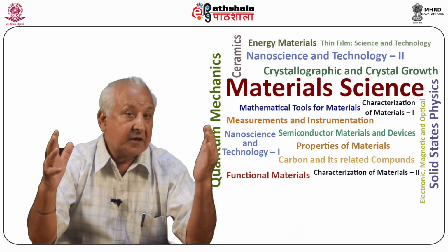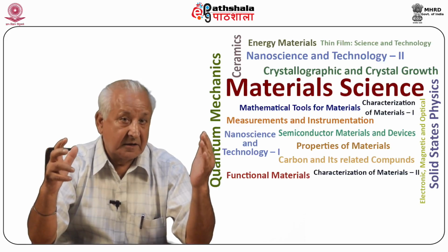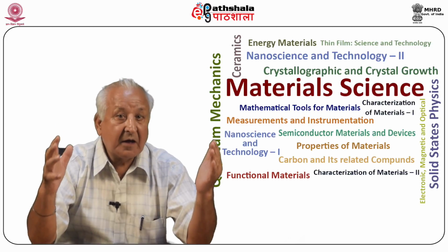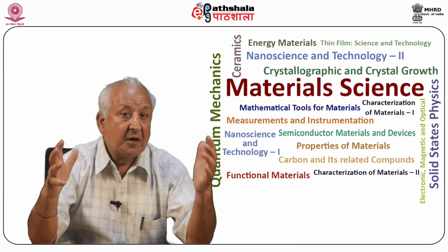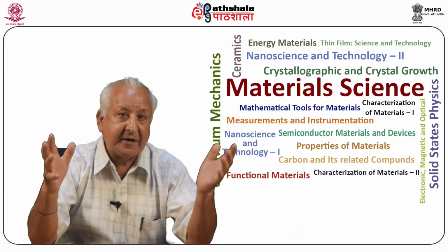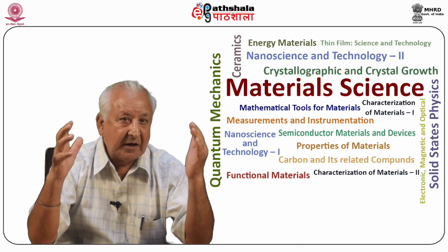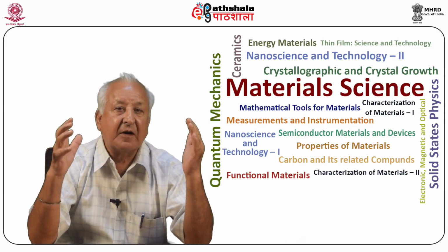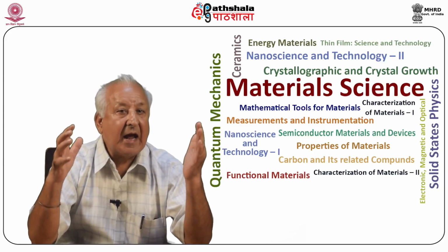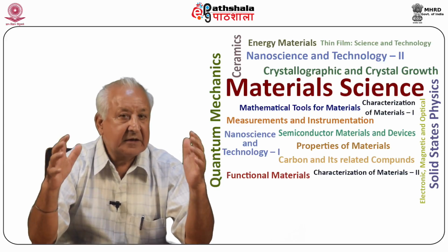The next major technique is growth from melt. There are subcategories in this category, like the Czochralski crystal pulling technique, Verneuil flame fusion growth technique, Bridgman-Stockbarger growth technique, and crystal growth by zone melting. Other innovative techniques that fall under the subcategory of related growth techniques include plasma melting, liquid encapsulation pulling, skull melting, normal freezing, directional freezing.